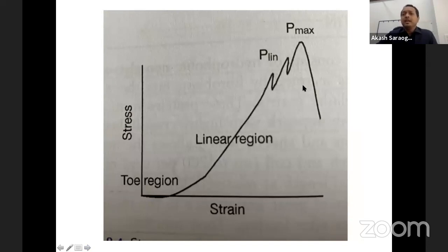So this is again a stress strain curve, and this may be put in your exam and asked, okay, can you tell me what material this is, what stress strain curve this is? So if you see, typically there is a toe region over here. This toe region implies that there is an increase in length of this material in the beginning without an increase in any amount of stress. So this is a graph of a ligament or a tendon.